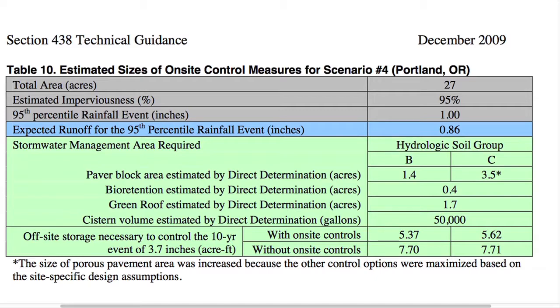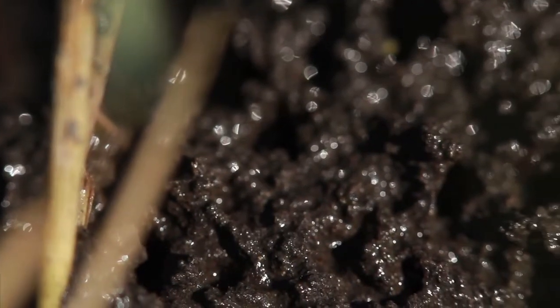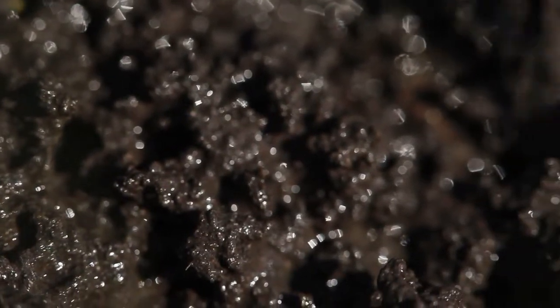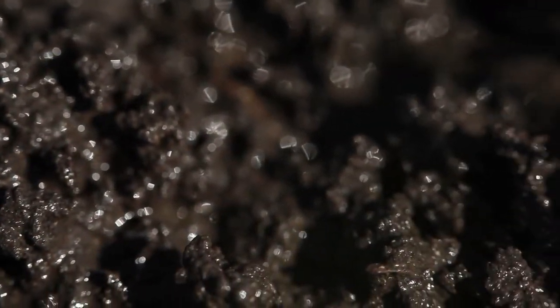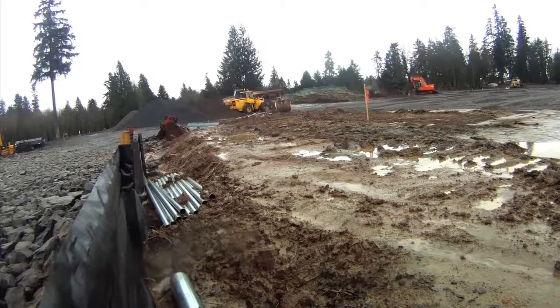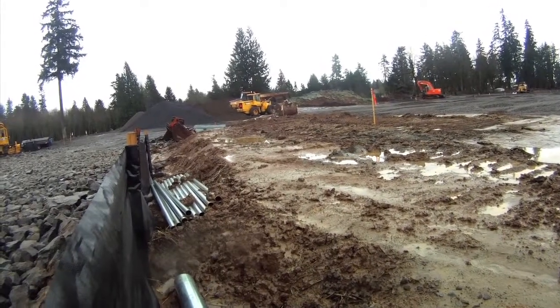The high percentage of imperviousness of the site, about 95%, requires that all infiltration designs be based on resident soil type and design volumes, or with adequate subbases or amended soils. Now, OSHA classifies soils into 3 main groups: Type A, Type B, and Type C. Type A is the most stable, while Type C is the least stable soil.